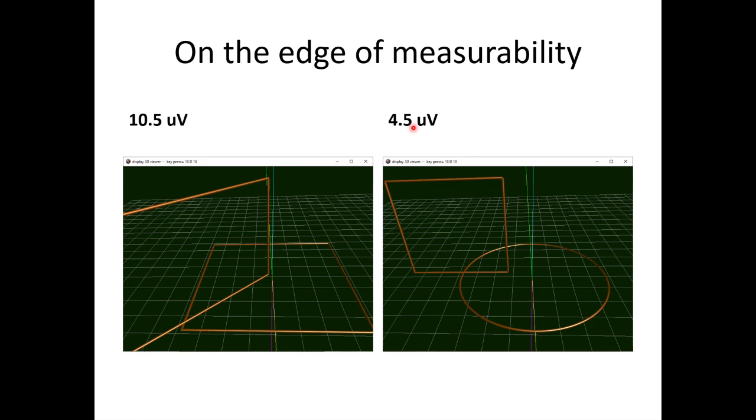But to get these effects, okay, we need the smallest piece of wire. We're going to take 30 gauge wires where we start. I'll explain how we got there. And we have to put 100 amps through it. Now, we're not going to keep 100 amps constantly. It's going to be pulsed. But we need 100 amps through 30 gauge wire to pick up these tiny microvolt values. So these loops here are probably going to be 100 turn loops so that this guy can be a full millivolt.